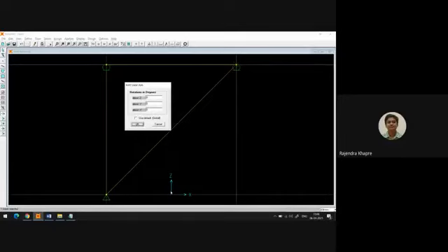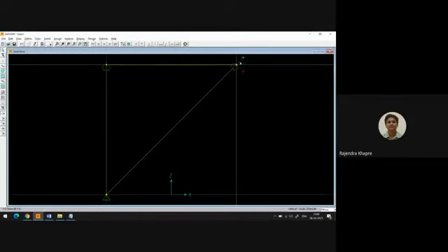Okay, so about the y-axis means perpendicular to the screen. So about the y-axis you have to rotate it by, say, for example 45 degree. Okay, if I change this to 45 degree, it will not solve my purpose, because you see the roller has been rotated in the wrong direction. Okay, so it has to be rotated in the negative 45 degree.